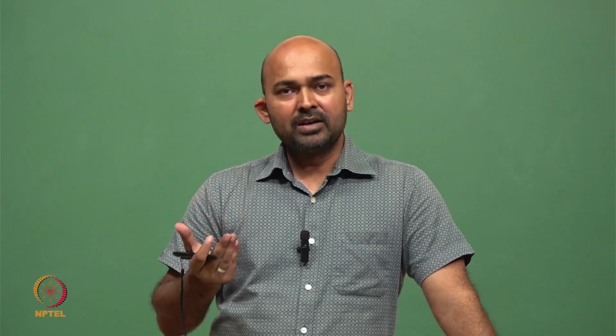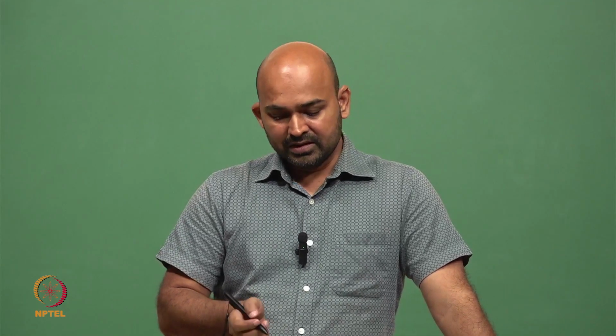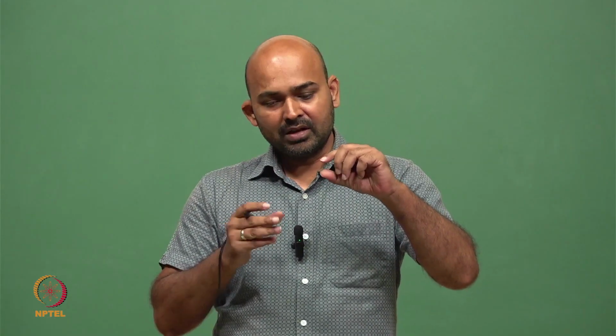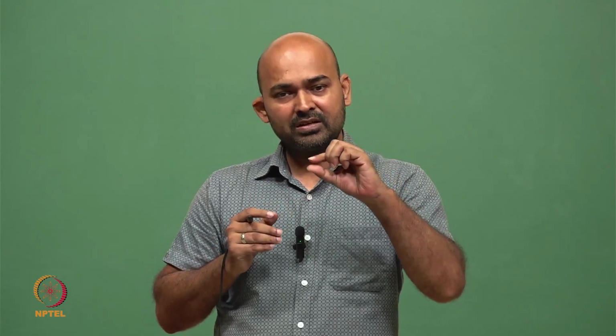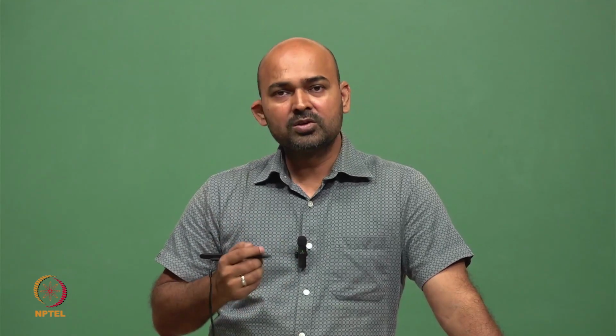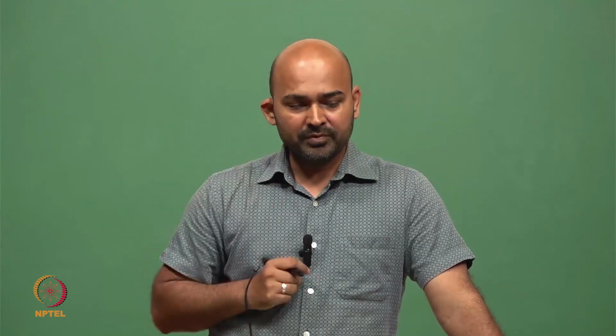Beyond those limits, we cannot increase the value of I, or we can reduce the thickness D so that sensitivity goes high, but that also has limitations. How thin we can go in that semiconductor plate or semiconductor film also has physical limitations. We cannot go to much thinner materials because of many other issues. So D also has certain limits. So the sensitivity is dictated by the current and the thickness of the material.